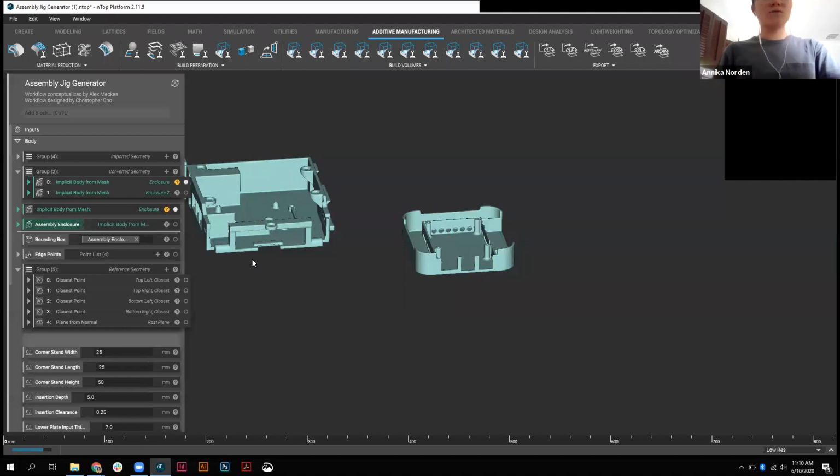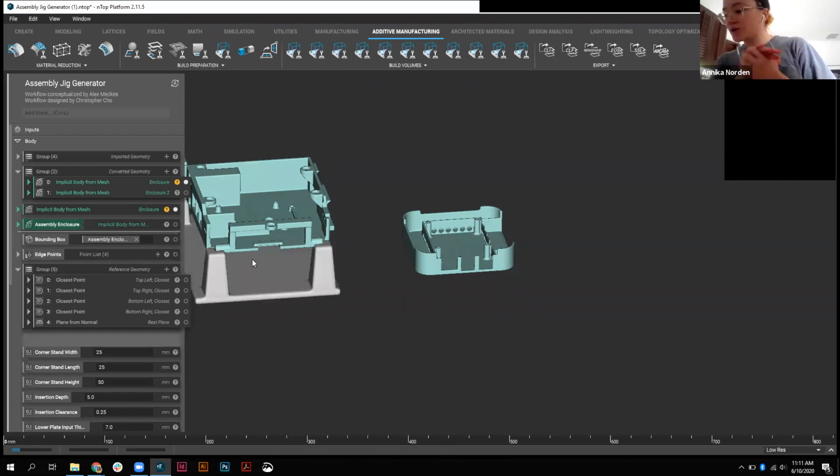As we let that run, we can start to think about how we're actually manufacturing this jig. You saw it's a pretty simple geometry, but maybe some of the next steps I could take would be to actually shell that part out, maybe chop off the bottom. So then we can use a vacuum form to actually create this part.